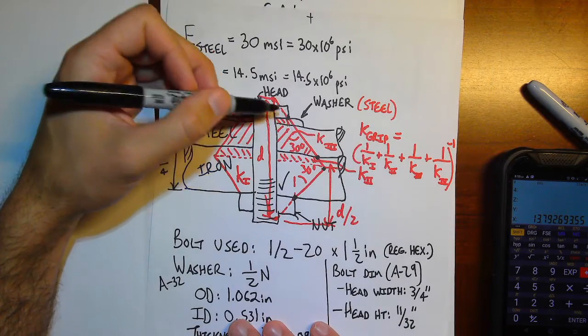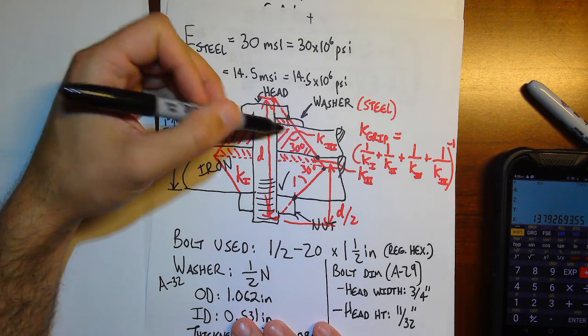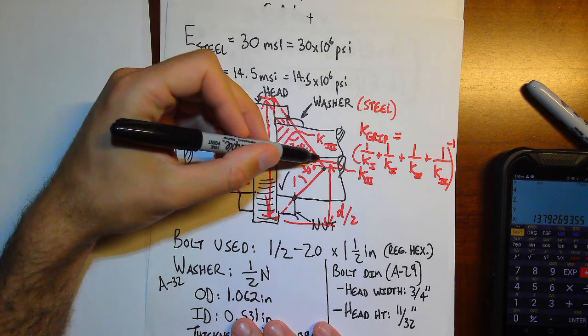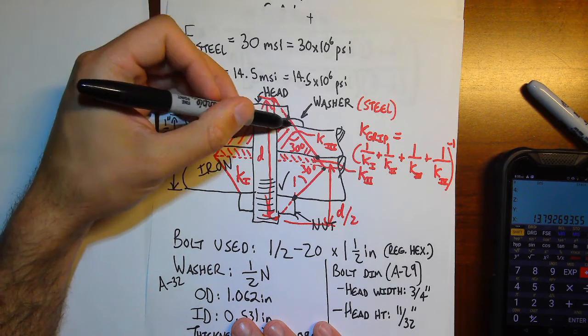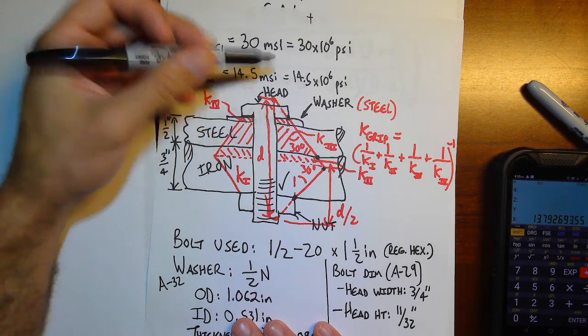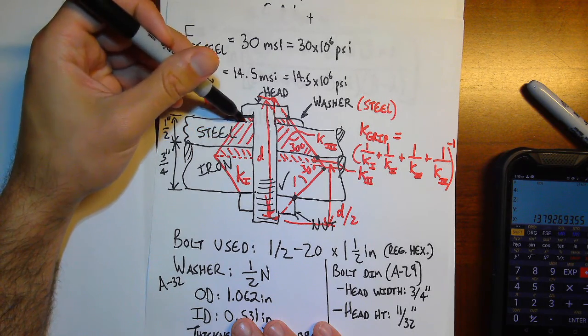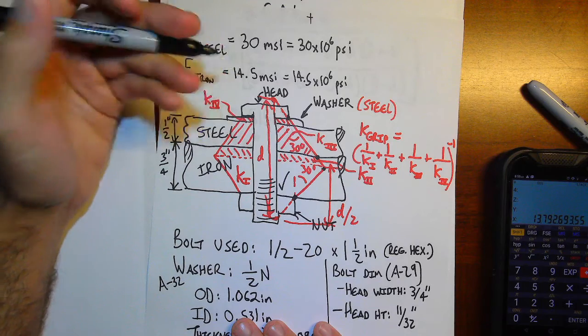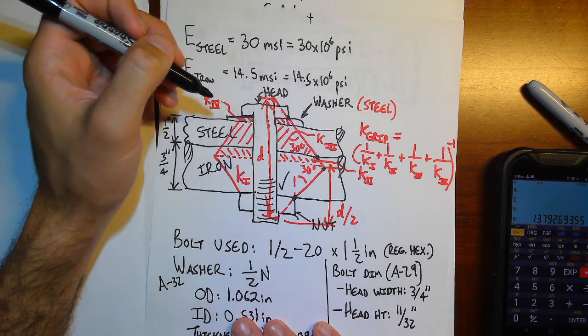Well, we don't necessarily change material here. But technically, I could just compute this entire frustum here in one shot. And so they're just computing it for K4 because both this piece of steel here and the washer are the same material. Technically, I could do that. You know what? We actually don't lose anything by doing that.